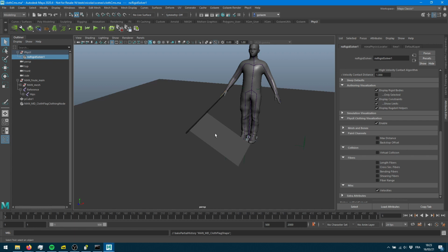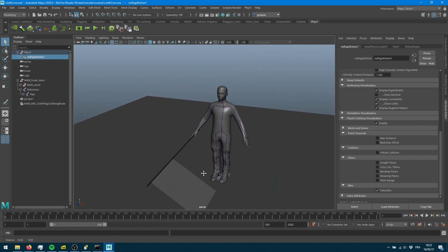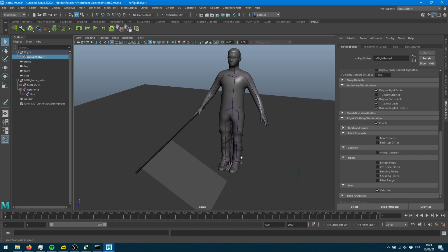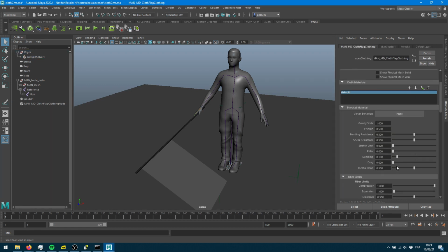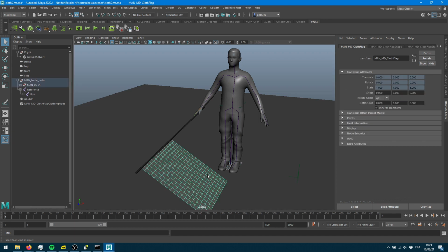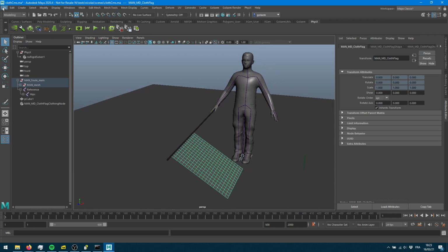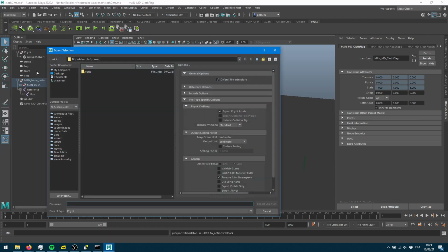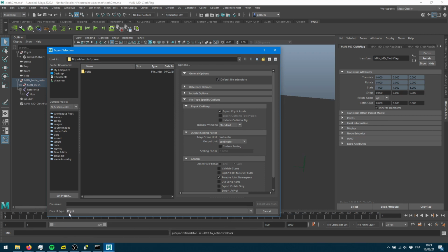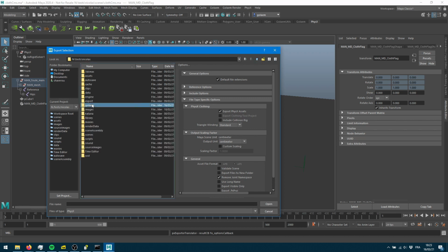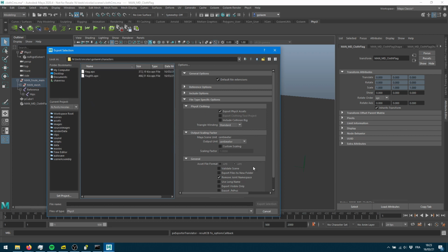Great. So let's say you're really happy with that system here. If we want to inject this into Golaem, we need to export those per vertex attributes and those cloth material attributes into a specific file that Golaem can reload afterwards. So what we're going to do is select that geometry there. We're going to go into the file export selection menu, and now into your drop down, as soon as you've got a physics plugin loaded, you've got a physics extension that you can apply onto your characters. So let's export this into a convenient space.